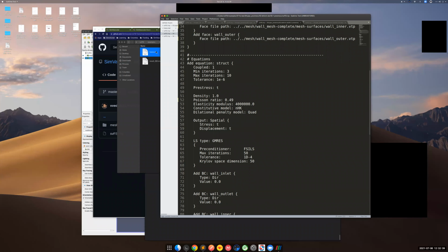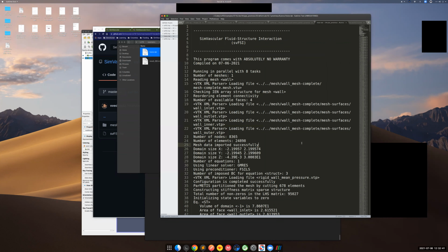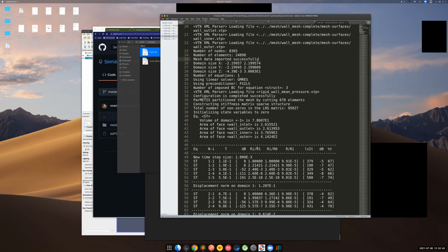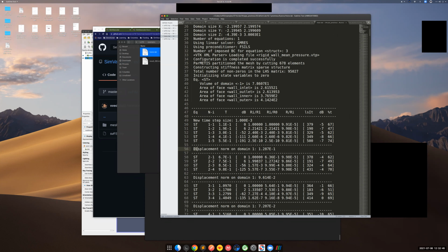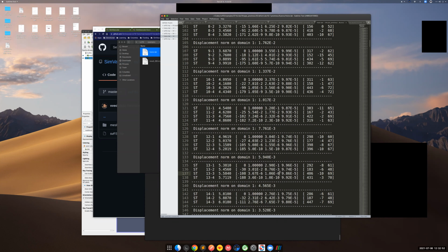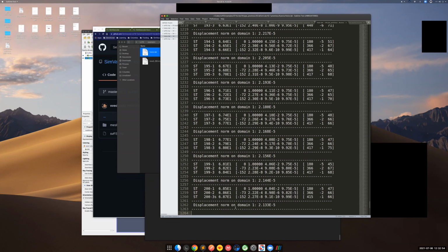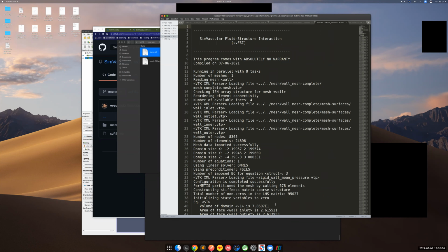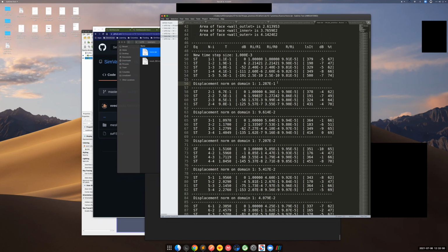Once you do that, you can see here the pre-stress simulation output file, where it also provides you a norm of the displacement. As it is pre-stressing, you will find that the displacement actually comes down. Once it converges to, let's say, a total norm of the displacement of the order of 10 to the power of -5, having started off from, let's say, 0.1, we're happy with this.